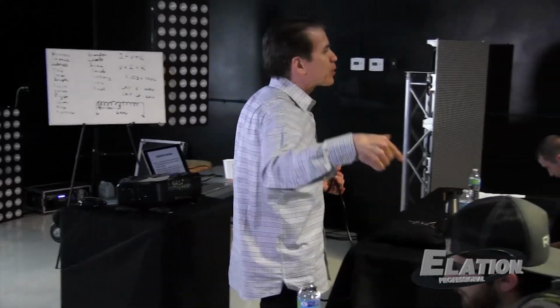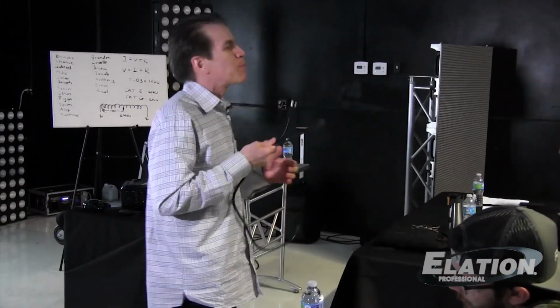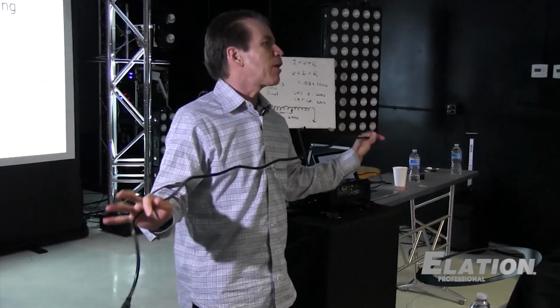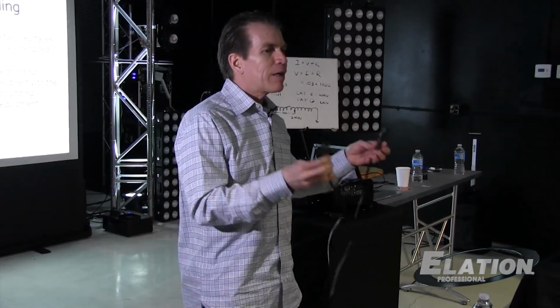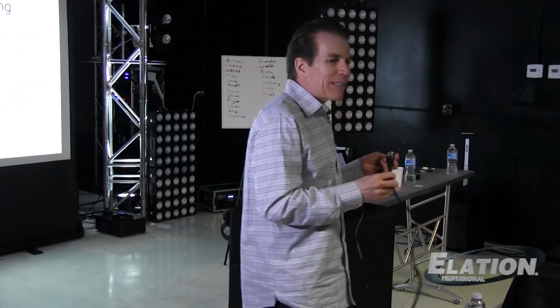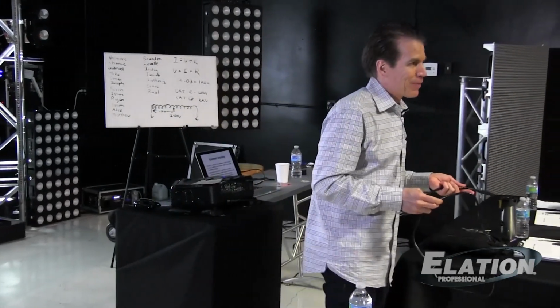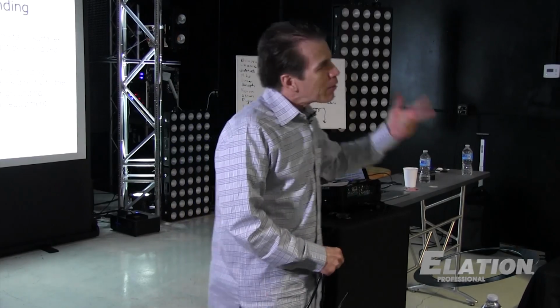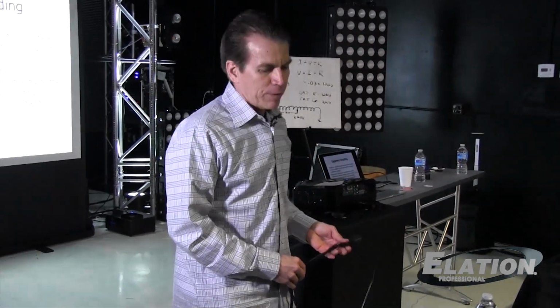And when something's brand new like this, chances are it's going to be good. It's once it gets put into a rental house and it's rented out over and over again, and it comes back, that's when you really need to be careful. What did they do to it? What abuse did it take? And is it still in good working condition? Right? So never assume. And that goes from the supply all the way to the load. That means your feeder cable, your connectors, your power distro, all of that stuff should be inspected as you're setting it all up.